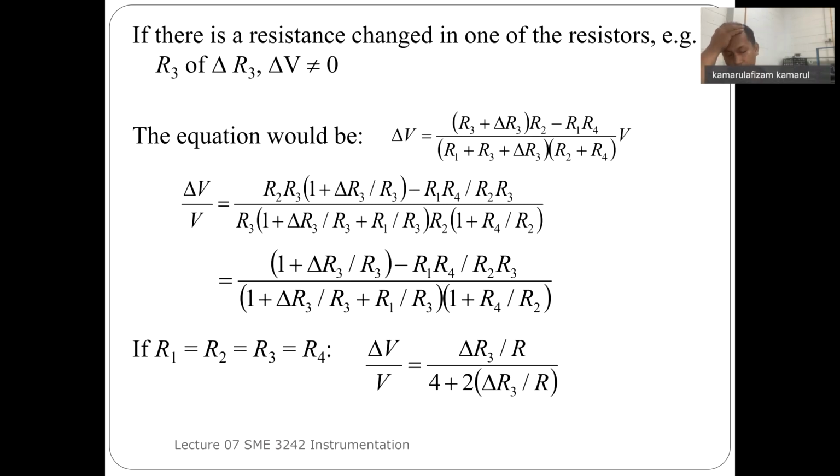So we are talking about null bridge. The bridge is more or less balanced. VA and VB are the same. You can take any value. It can be 0, it can be 4 volts, it can be 2 volt, it can be 1.5 volt. VA and VB are the same, so the potential difference is 0. Basically, it's a null bridge, a balanced bridge. V out is equal to 0. For this particular setup, the V out is equal to 0.